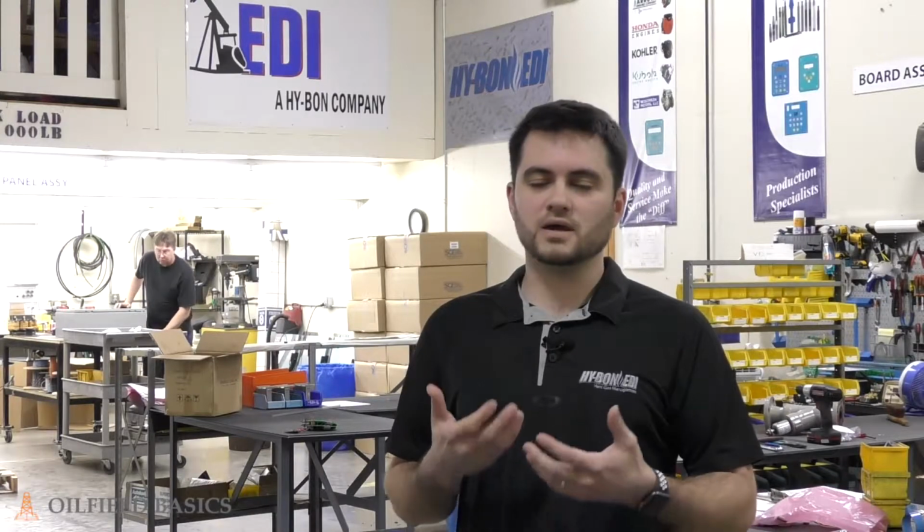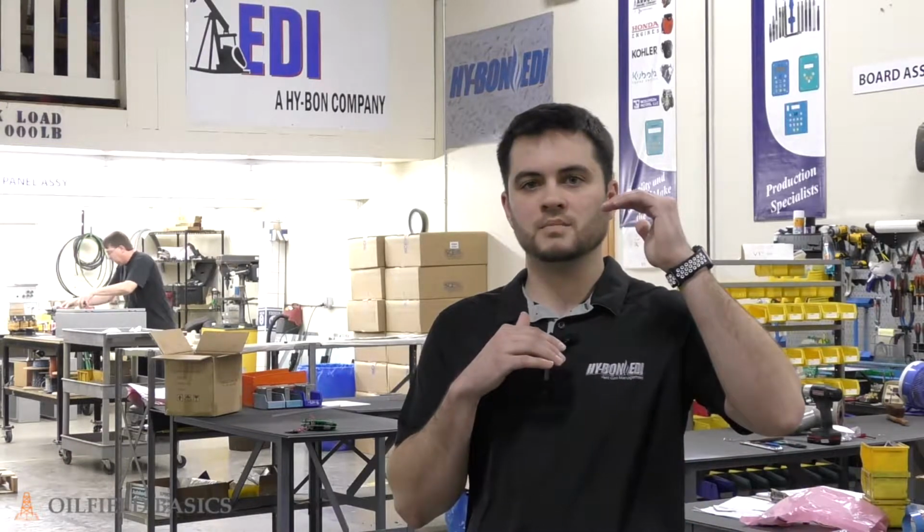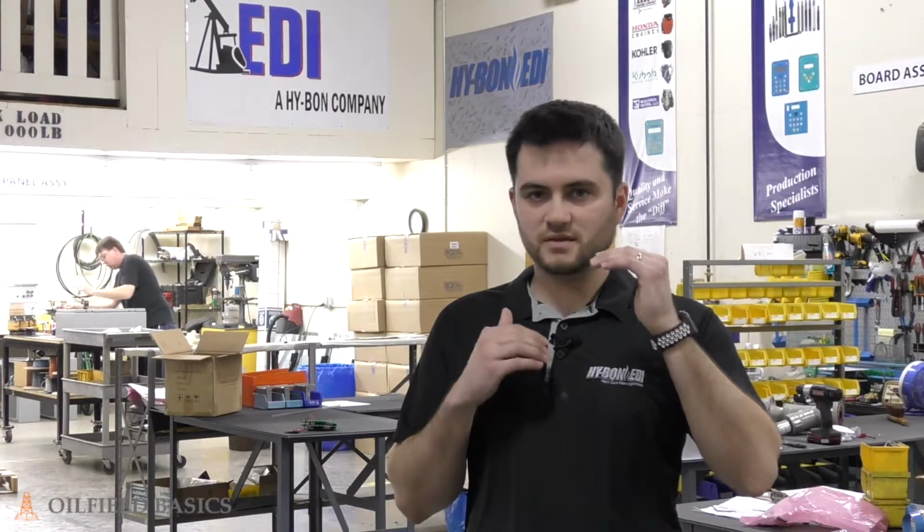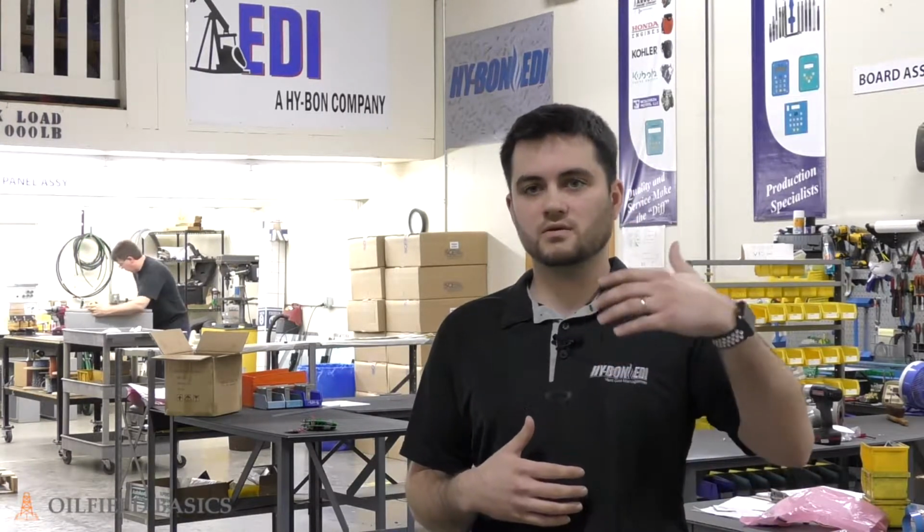A natural draft combustor is typically the most common enclosed combustor that you're going to find in the oil and gas industry. The reason for a natural draft combustor versus, say, a mechanically actuated and automated combustor is that the airflow, the air being pulled into the combustor, is done naturally. The way that the airflow is pulled into the combustor is through what's called the stack effect. The stack effect is simply a difference in air densities. And when you have a difference in air densities, the air begins to move, begins to flow. Well, that's created in our application through strictly temperature difference. As the temperature within the stack begins to increase greater than the ambient temperature, you have a natural flow of air being pulled into the combustor.